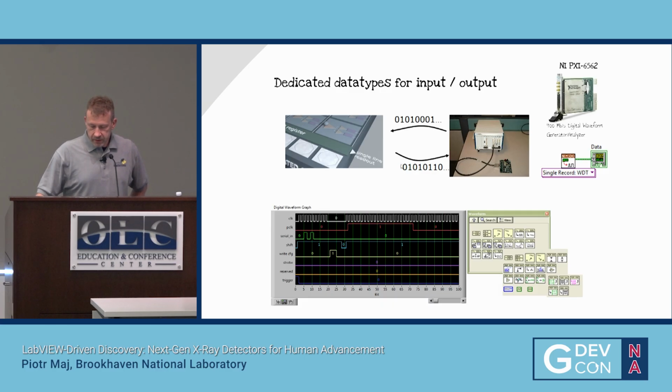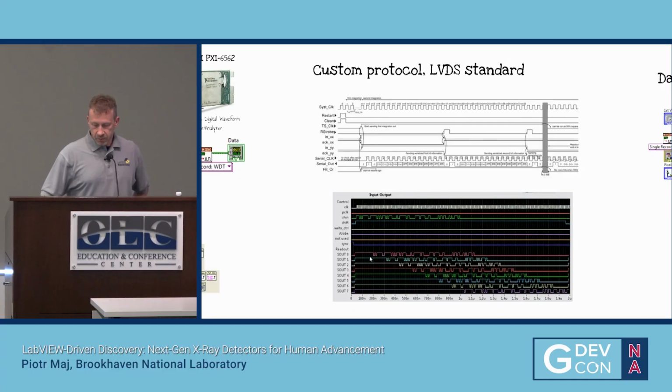And surprise, surprise, LabVIEW has a dedicated digital data type and the digital data graph, where you connect graph directly to the function that performs the acquisition from waveform generator analyzer. You can see your protocol right there. You can just inspect visually if everything works fine or something's wrong.